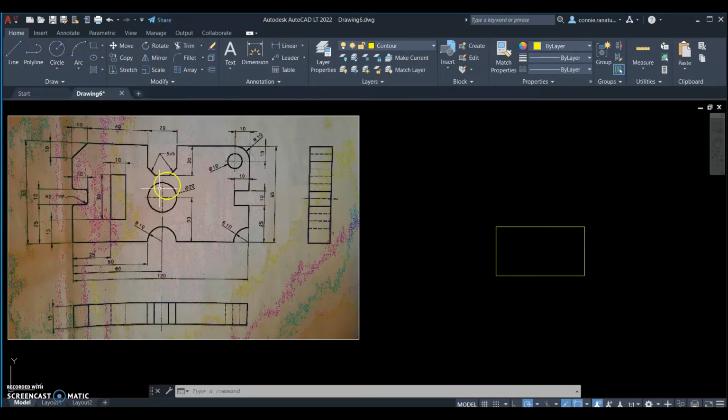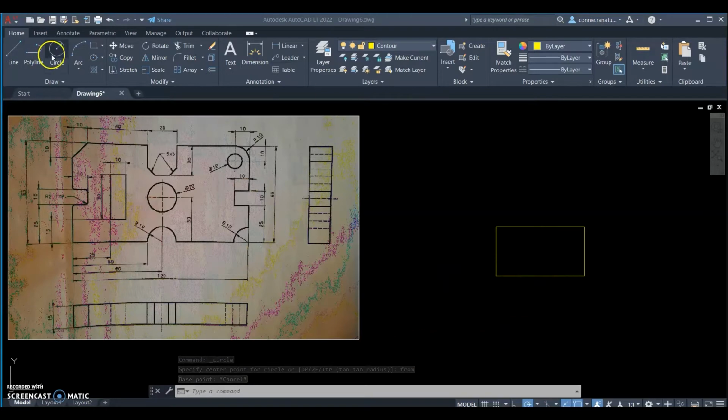So now we should maybe take the circle first. We choose circle and it's going to be 60 in the x direction and 30 in the y direction. So I write here down in the command field snap from. Enter. I will try again.